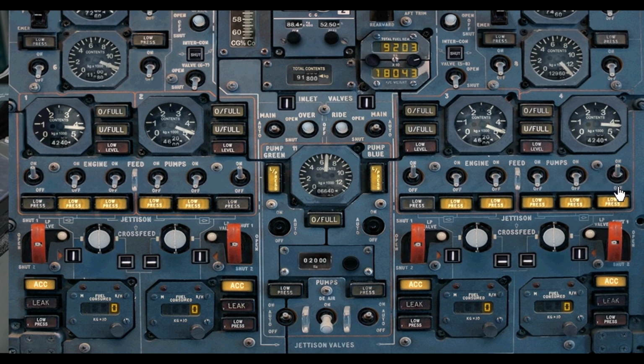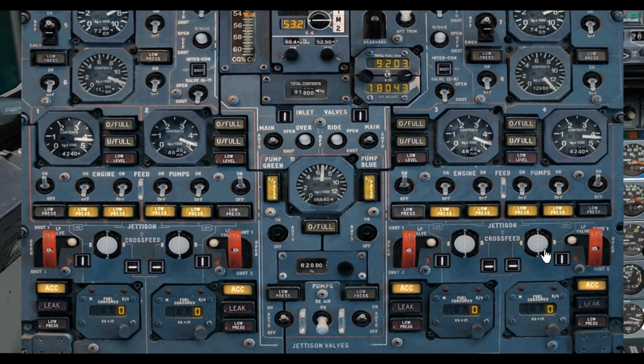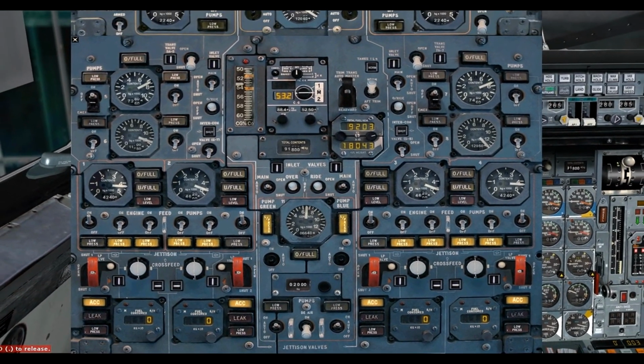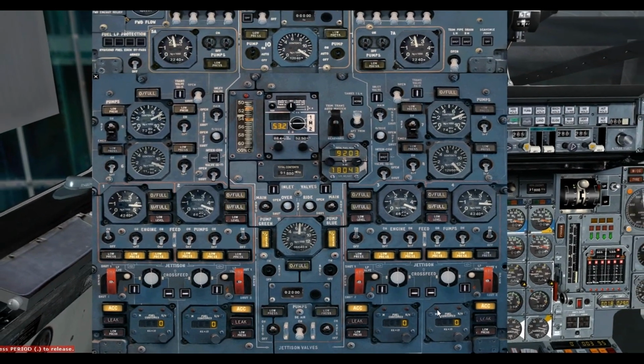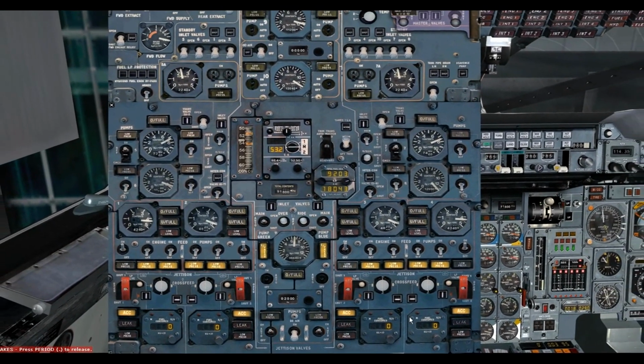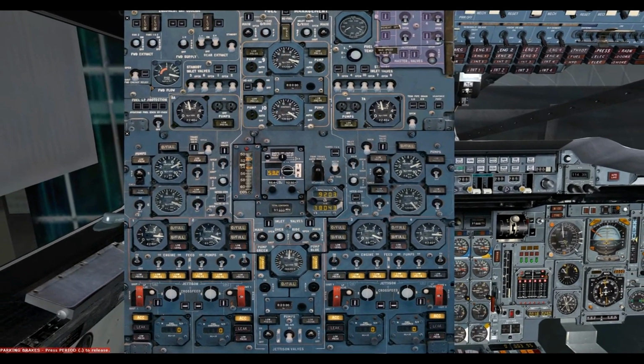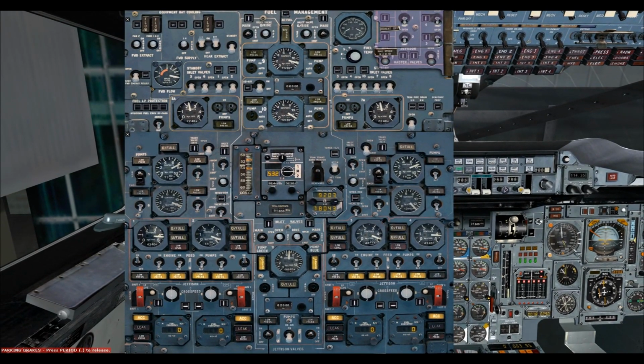So now our panel is completely set up correctly for our engine start, and once we start up the engines, we'll proceed item by item onto the next part of our panel. One last thing over here, the main trim transfer. Our trim transfer should be closed and guarded, and our aft trim should be on normal. And you can see here the MI, the mode indicator, is normal.